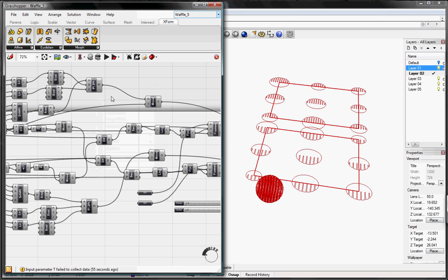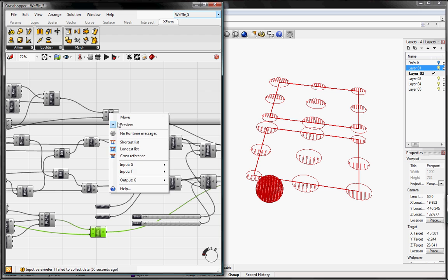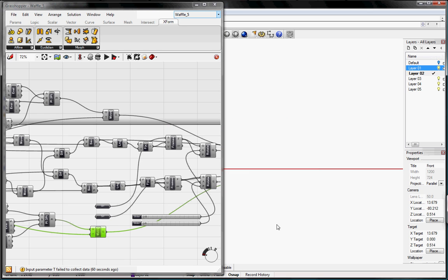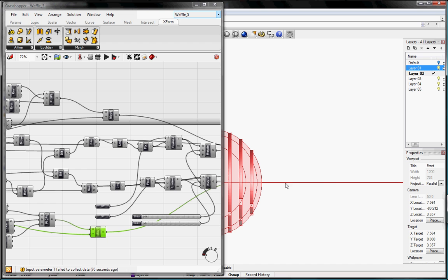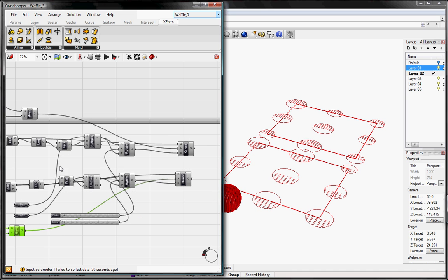And then I'll turn off the 3-point plane, and I'll turn off the Move. Then we'll go back to our left or right view, and as you can see now it's perfectly flat on our surface. So that's how you lay them out on surfaces. In the next tutorial we'll put text tags on them so we can remodel this together using the computer as a reference. Thanks for watching.